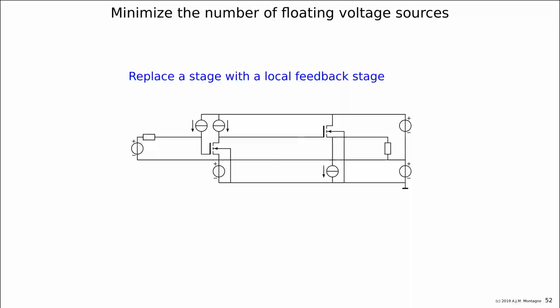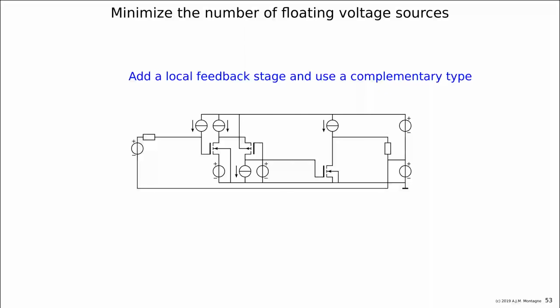And we can also do it with a common gate stage, inserting and then flipping the whole thing. And then we do it like this, and we call this a folded cascode. You know this circuit probably as a folded cascode, but it's also a way of just creating a level shift. Maybe you don't need it at all for elimination of the Miller effect in the first stage, because that was the purpose of placing a common gate stage as we have discussed it.